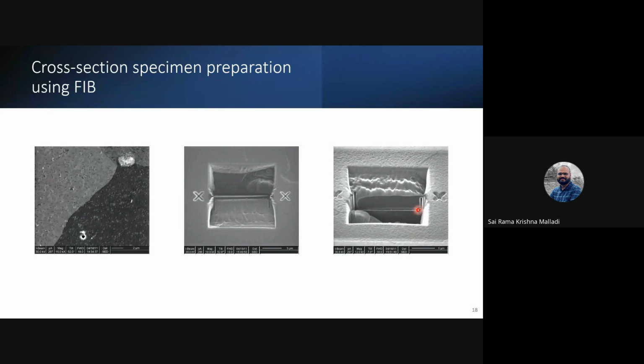So this particular characterization technique, by a combination of scanning electron microscope, FIB, TEM, cross-section specimen preparation, and so on, I start looking inside the materials and I establish a link between the internal crystal structure, the microstructure of a material, to the properties of the material. So that is the whole aim of this characterization of materials.